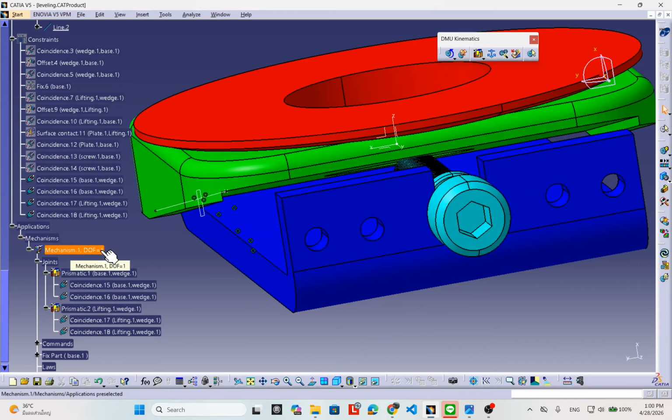Right now, the degree of freedom one, right, is not completed. Should be 0. The program allows you to simulate your mechanism, and if it equals one, you cannot simulate your mechanism anymore because it's one left. You must assign the one left degree of freedom. Right? Right now, it's not completed. Assign all of the pair. Right? In this case, it's pair number one, pair number two, and not enough because it's less by one degree of freedom, not completed assign.